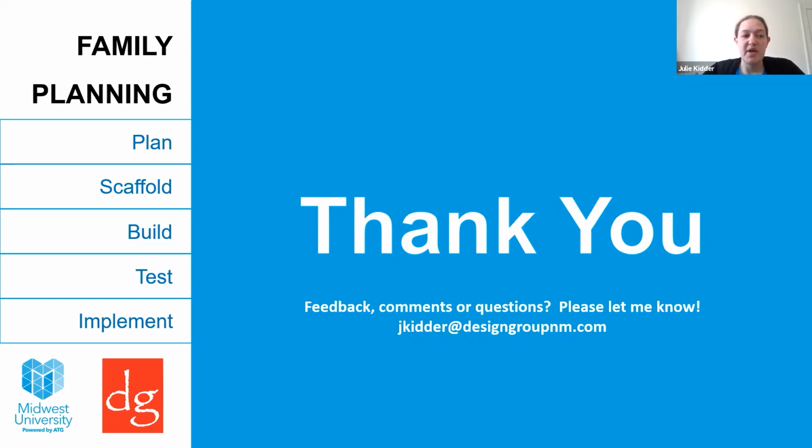So, I use set parameters for everything that controlled the way hinges and leaves and frames sat in the model. And materials obviously were grouped together. Dimensions were pretty straightforward, but I sort of took some of the other parameter groupings to make sure that they grouped separately and made them a little bit easier to find. So graphics was where swings ended up, whether or not it was for graphics, it kept them separate from other